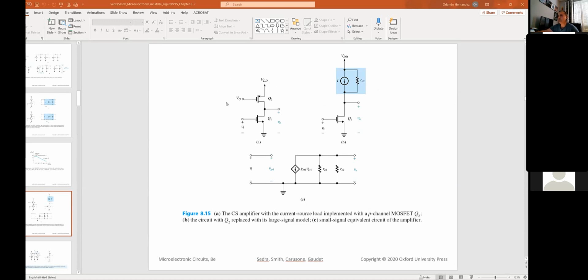So now, when we put this transistor with a constant VG that we use current mirrors and biasing and current steering to generate, this is a constant voltage that sets that drain current through Q2, and that is our load to the common source basic gain cell or basic gain transistor Q1 of this amplifier. We have our amplifier, and from a small signal perspective, it looks like part C of this figure, okay? And that's what we're going to be talking about next, okay?